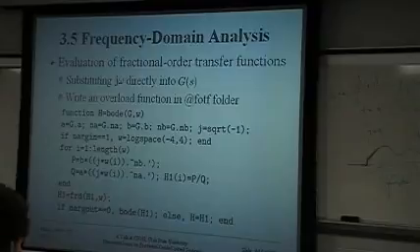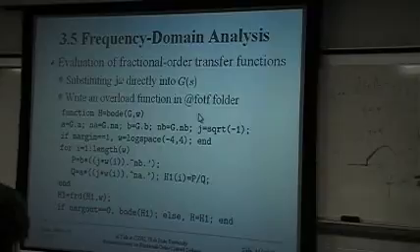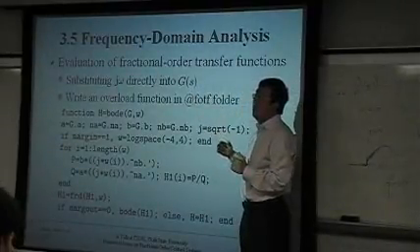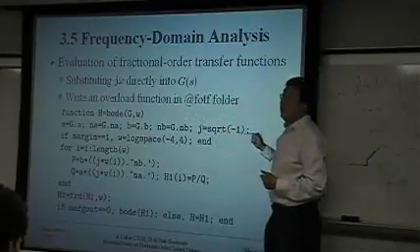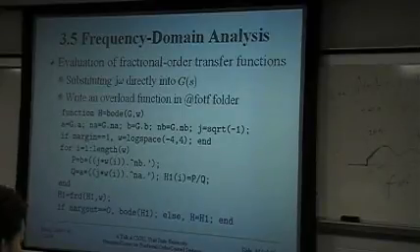And by using this, I have defined the Matlab function called bode, which has the same name as the one for integer order systems, and still we have to put the function under this folder, otherwise there might be a conflict. We have to put it under this folder. And now we can use this function to draw the Bode diagram for the system.